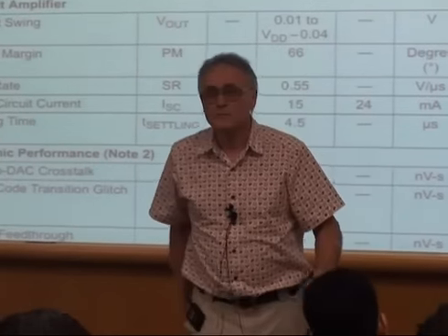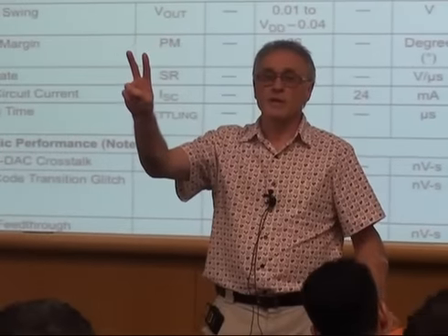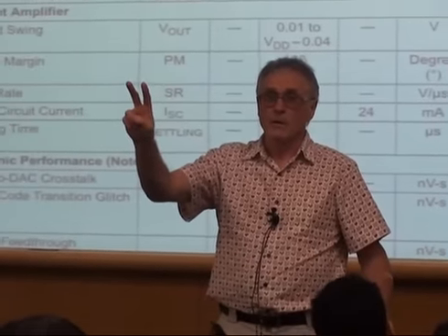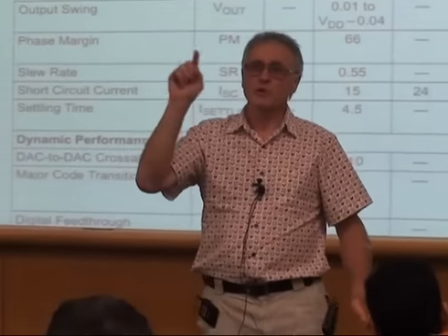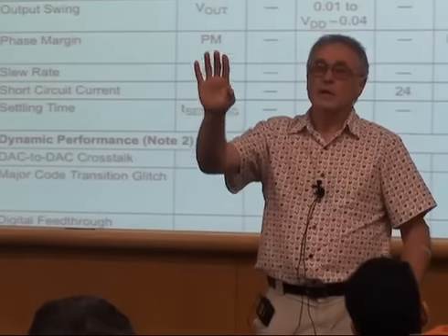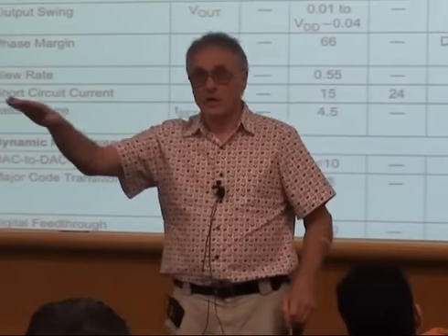Because you can load two separate voltage channels, I mean one after the other. So you load channel A with one 16-bit transaction. You bring chip select up, you bring it down again, and you load the other channel.